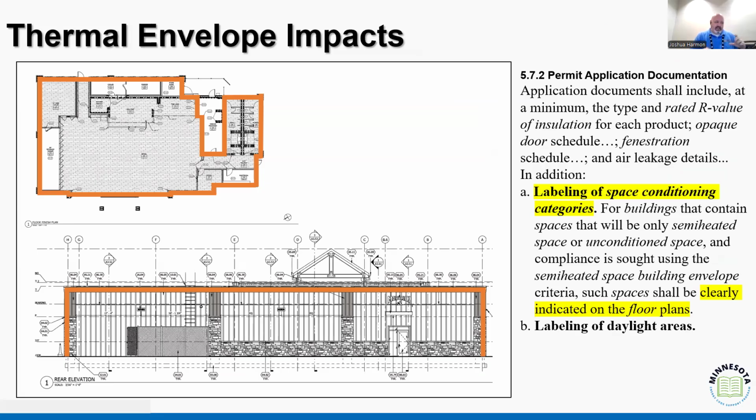We're going to see, again, that we've labeled these areas, right? This is the conversation I get into all the time. Is this conditioned? Is this semi-heated? Well, if it's semi-heated, then I'm trying to isolate it out of my building, right? I'm trying to carve it out so that I'm controlling the conditioned space, right? The semi-heated, yes, there's some expectations, but it's semi-heated. It's not designed to be as controlled as my heated spaces, right?